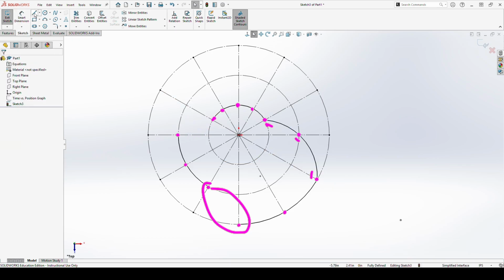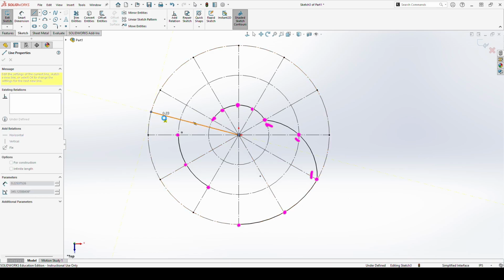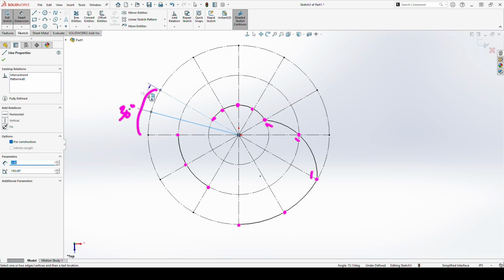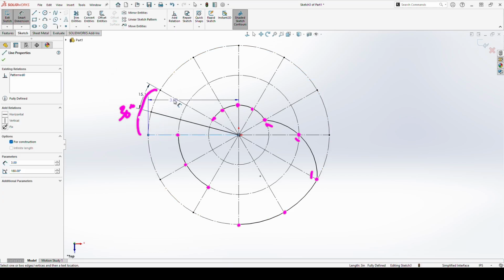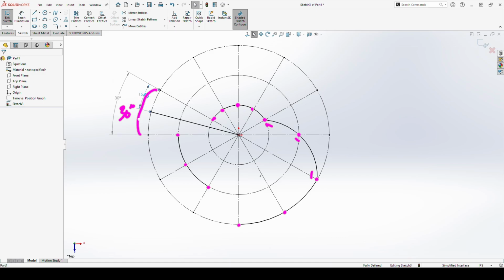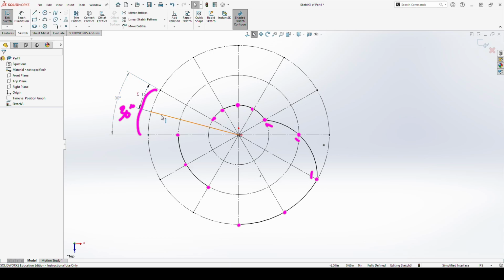So with that, in order to fix this, I'm going to go ahead and I'm going to break this 30-degree segment into 2 parts. It should just be set to 15. I set it exactly at half, making a driven dimension so it doesn't end up doing anything, and just using equations for this. Definitely not required. We could have just written 15 degrees in there, but do whatever sometimes.